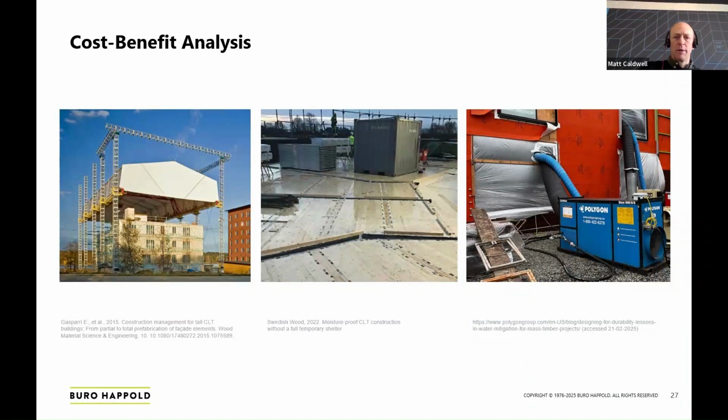Likewise, active dehumidification and drying of your structure could be viable, but again, it's got cost and time implications. Maybe it's something that's only really viable once your building's closed in. So maybe if you're doing a load of plastering and creating high humidity at a late stage, that might be appropriate. And if you are doing retrospective drying because you've got a problem that you didn't foresee, that is going to be very costly and take a lot of time. So again, that's really your last line of defense. You don't want to be planning to use that, I'd say.